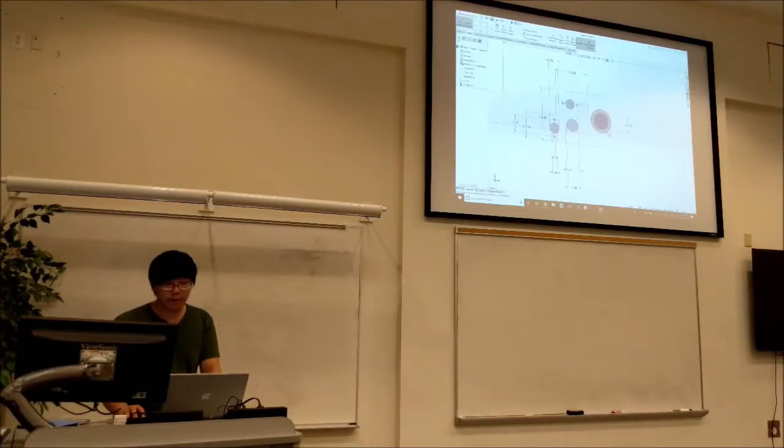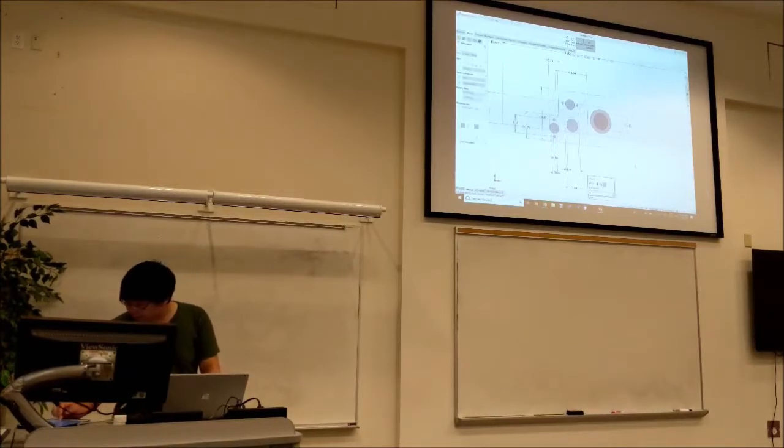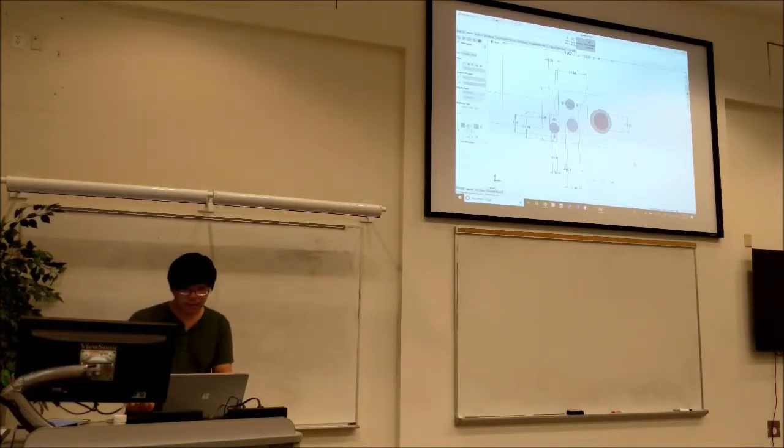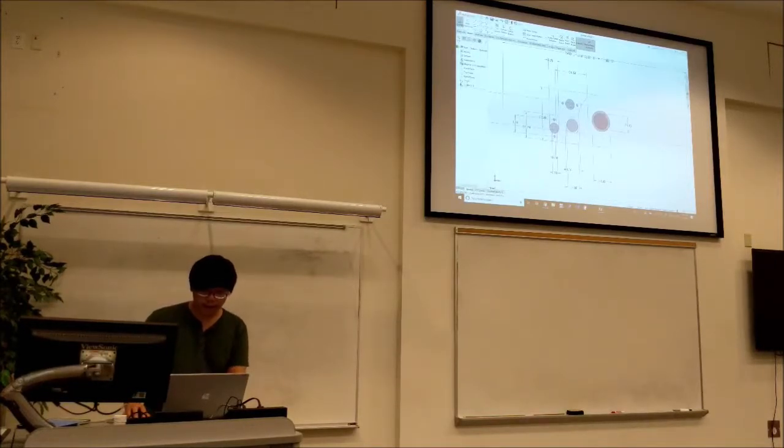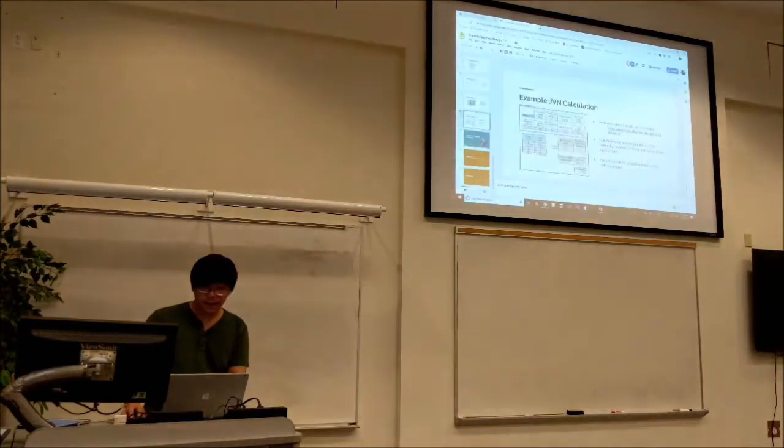So we're going to model this as the diameter of the sprocket, which is 1.432 inches. And again, if we look at JDN, that's the pulley diameter, because your sprocket essentially acts as the pulley of the system.